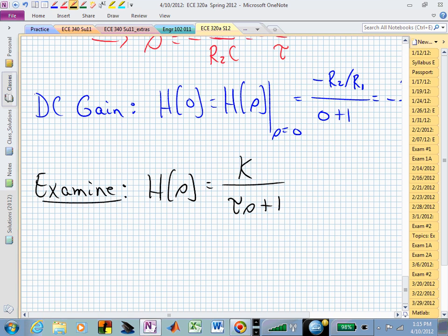But now we're just going to say, okay, let's have a gain K and a time constant tau. What's my DC gain of this H of s? Capital K. And my pole, where's my pole? Minus 1 over tau. All right.